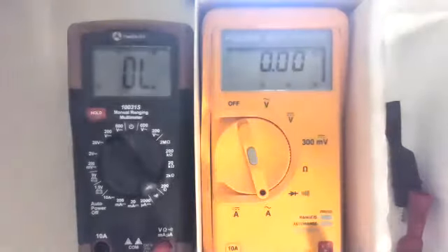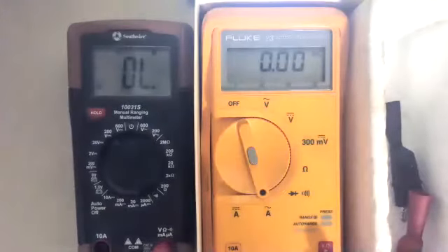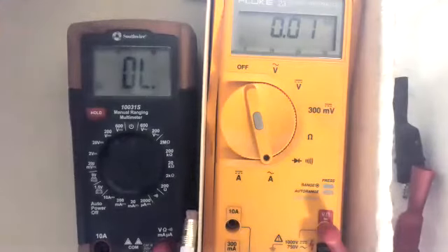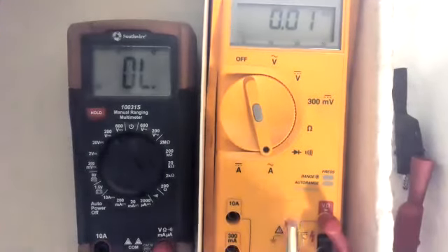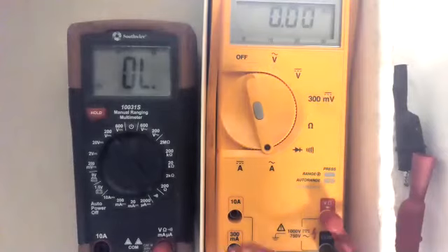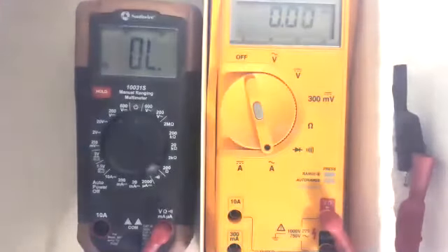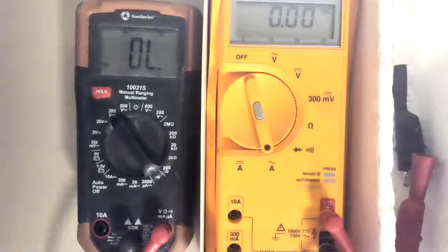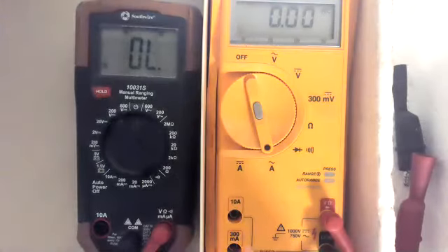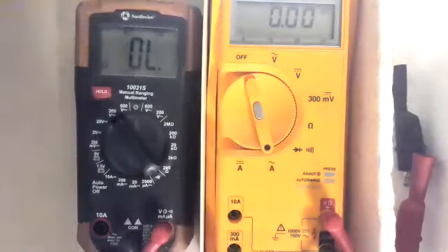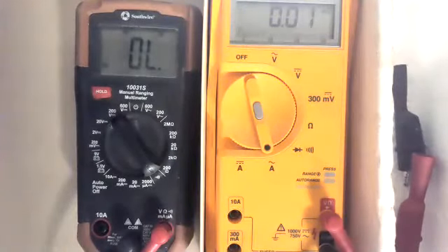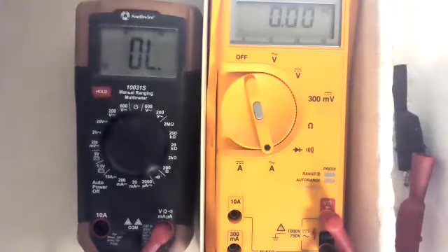So these things here, you can see, like this one's only good for 10 amps right here, and 300 milliamps. That's not very much. In the electrical world, construction, you're usually dealing with more than 10 amps. I mean, your smaller stuff could be around 3 or 4 amps, but you got to figure your breakers on your house are 15 amps, and then you load that 17%, or 20 amps at 17%.